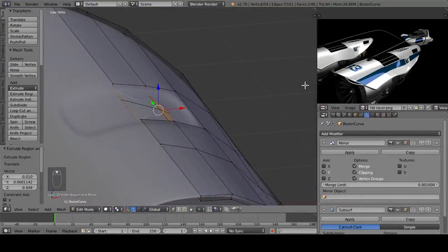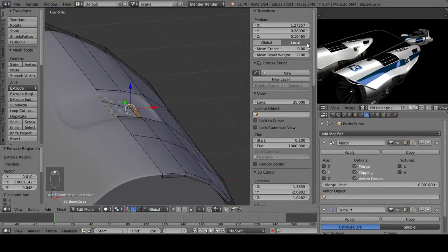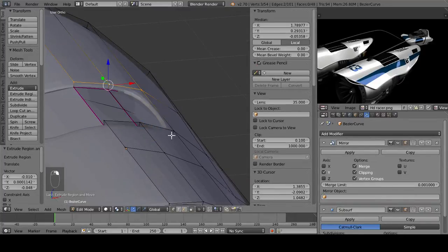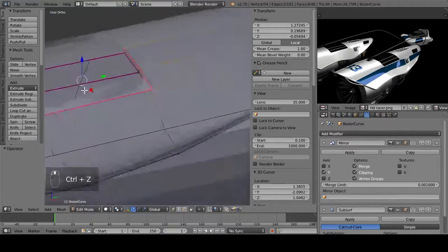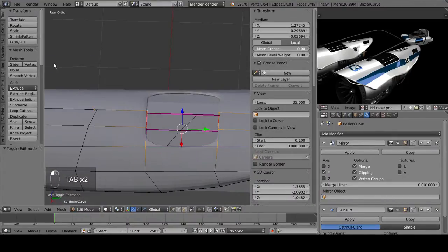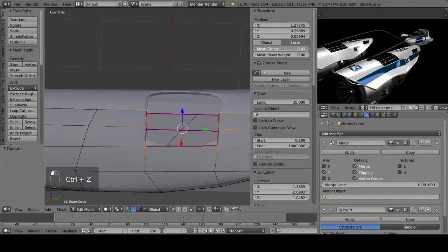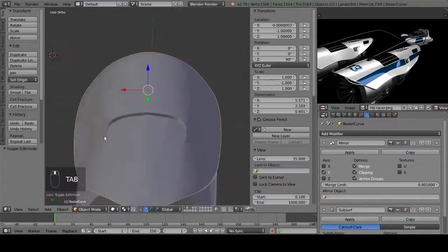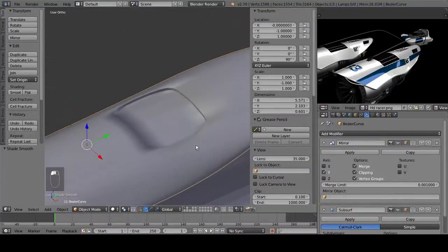because everything is very flat. So the best way to cover this for now is to hit the N key, and at the very top here we have mean crease, and this will just force all of our geometry to be nice and flat. Now personally, mean crease is very nice in what it does because it doesn't add to your geometry, because the other method of doing it is to create a loop cut and line it up to the edge. So for now we're going to use the mean crease, but I found that when we actually get into it, using the loop cuts works better, because if we put this into smooth we have a shading issue here, but